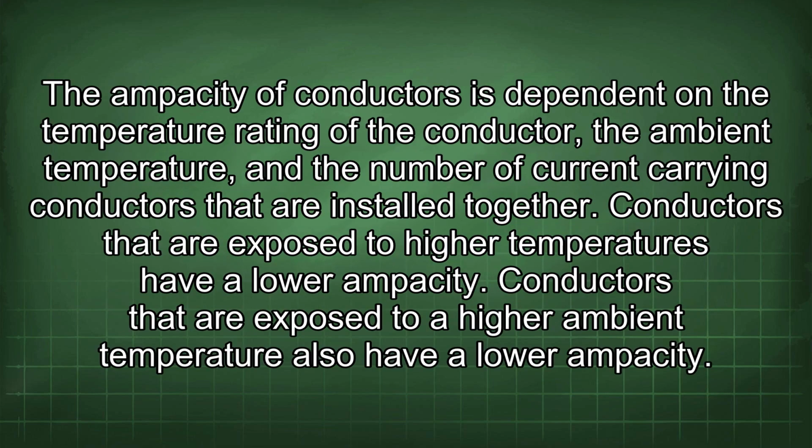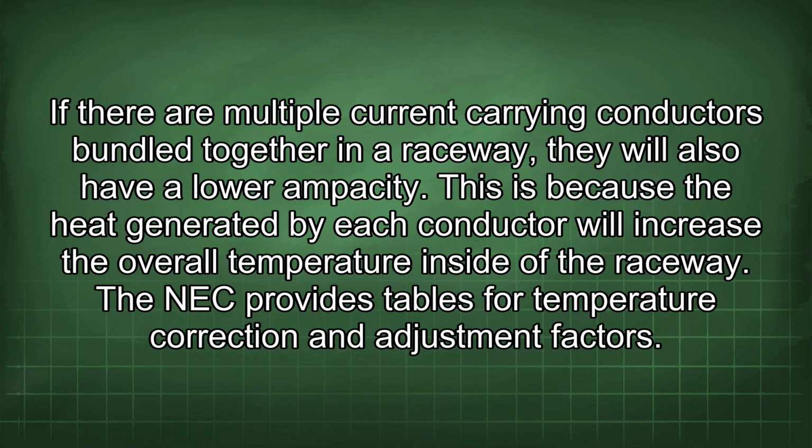The ampacity of conductors is dependent on the temperature rating of the conductor, the ambient temperature, and the number of current-carrying conductors that are installed together. Conductors that are exposed to higher temperatures have a lower ampacity. Conductors that are exposed to a higher ambient temperature also have a lower ampacity. If there are multiple current-carrying conductors bundled together in a raceway, they will also have a lower ampacity.